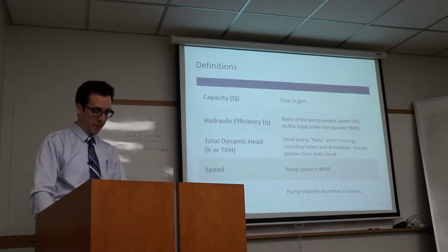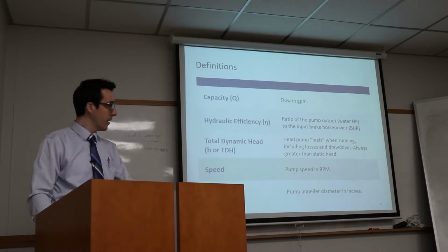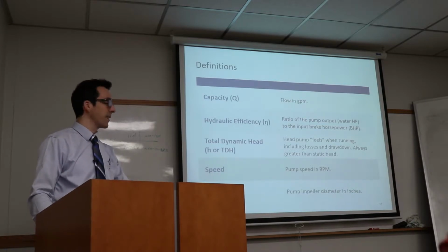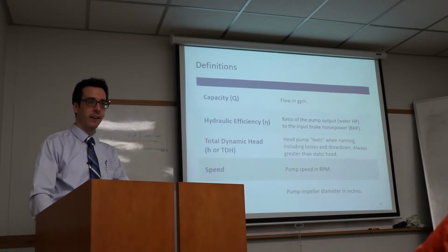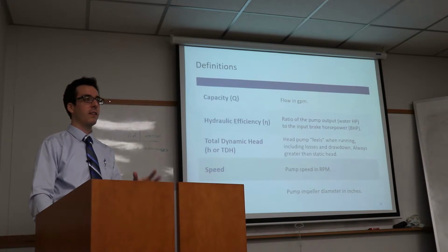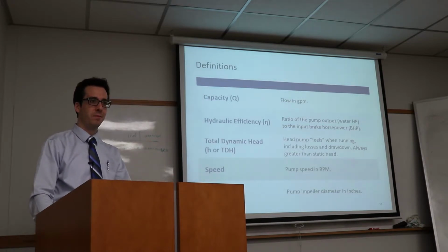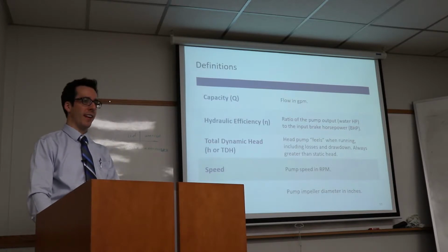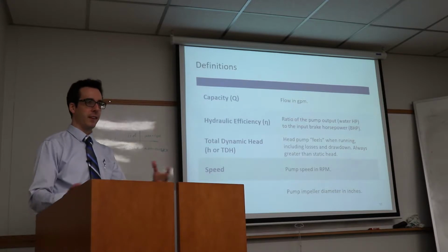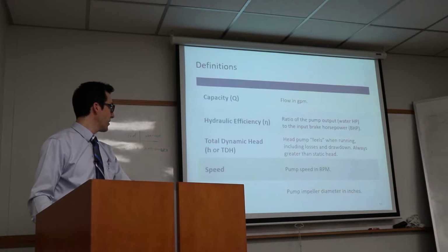So a few definitions we need to know before we can introduce the pump equation are capacity. We call that Q, flow rate. In this case, throughout this presentation, we're talking about water. It's incompressible, standard pressure and density, temperature. So it's a lot easier to work with than like compressed air and other things where you have to consider ideal gases and compressibility.